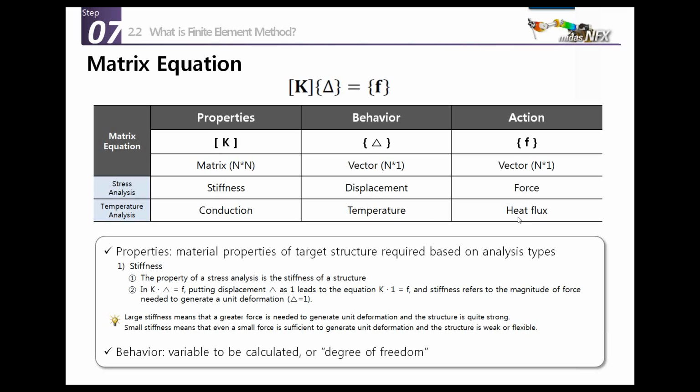So basically, to explain very simply what you get, you know the K matrix from the material data. The F is given from the boundary conditions that you apply to the model. So the only thing which is done is to invert this matrix and to get the displacement through the finite element method, linear static method, I mean.